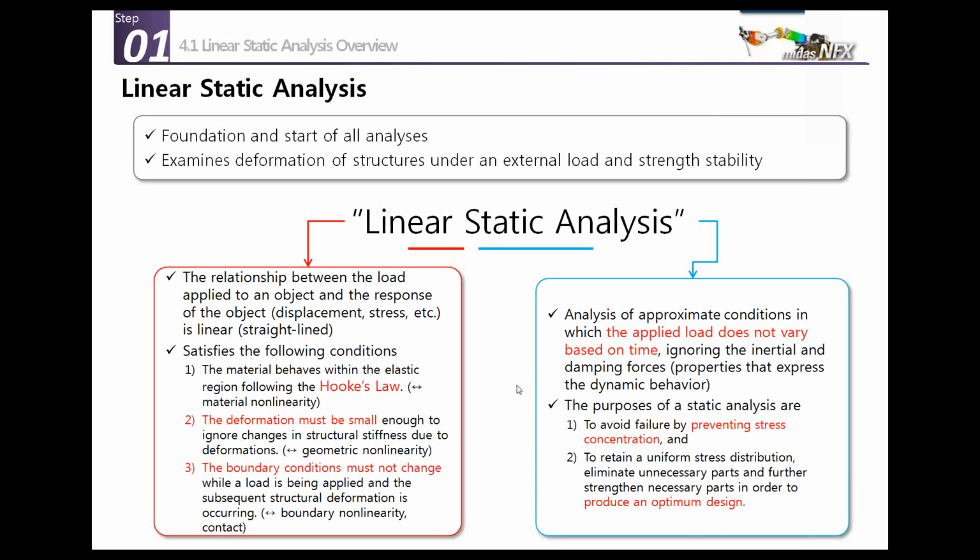So what it means is that linear static is basically just to check if your model is strong enough, and if it's not going into the plastic area. You check the safety factor of all the areas of the model, and if your safety factor stays over 1, it means that your model is still in the linear domain. Then you can check where the stress concentration is and improve your model accordingly. So you can see if your design is good or bad and improve it.